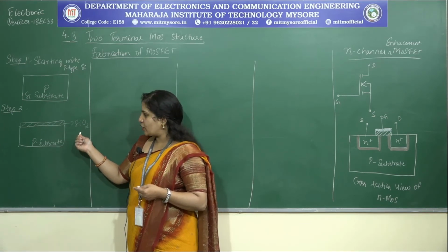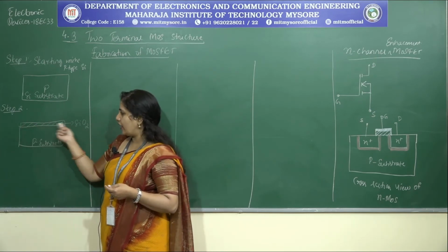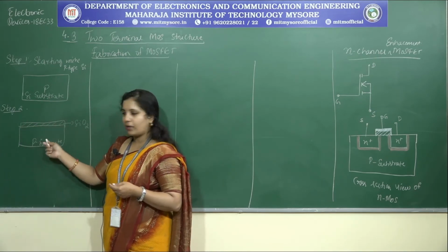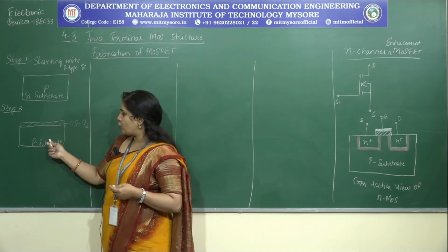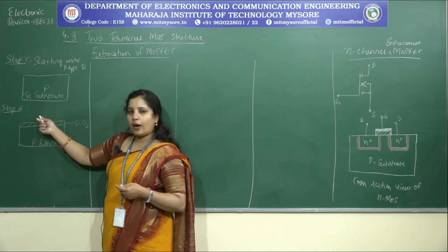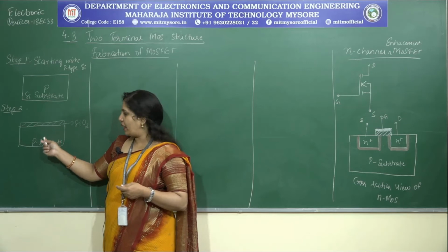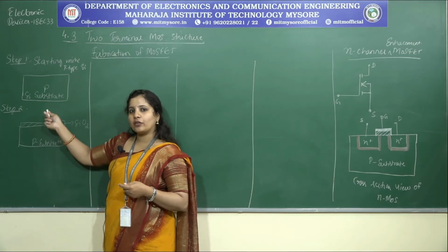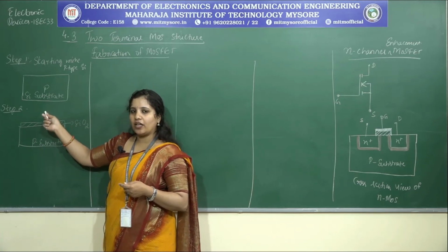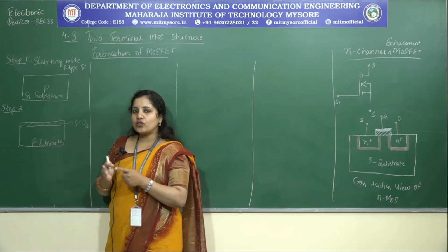Why am I creating this insulating layer? If I grow the silicon dioxide layer completely upon the P-type substrate, then I can ensure that this semiconductor will not react to the upcoming layers at unnecessary regions. I can make this P-type substrate have contact with the upcoming layers only at the regions where I wish to. Or else I have to isolate them, right?